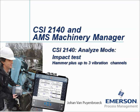CSI 2140 Analyze Mode Impact Test: Hammer plus up to 3 vibration channels. My name is Johan van Pijnbroek, and in this video tutorial I will show you how to use the CSI 2140 machinery health analyzer to perform impact testing, where one channel will be an impact hammer and up to 3 vibration sensors can be used to measure the response.